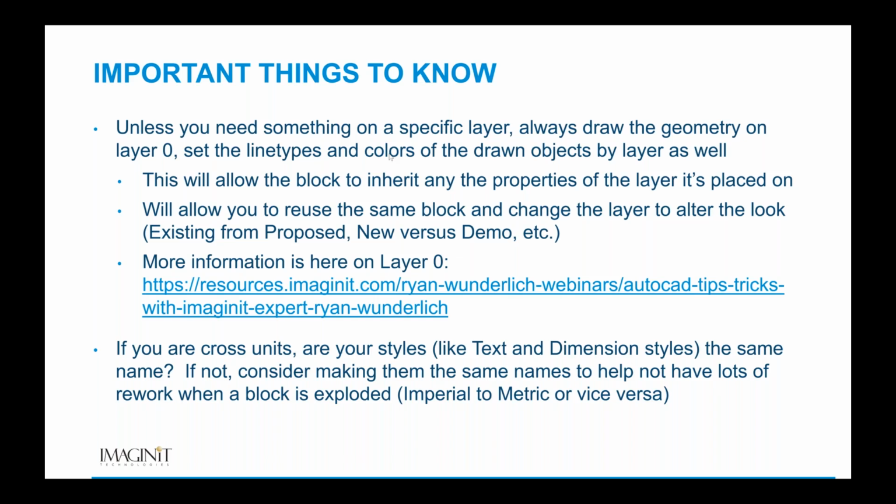Now, if you are cross units, i.e. if you work in both the imperial and the metric, are your styles, like text and dimension styles, the same name? If not, consider making them the same names to help not have lots of rework when the block is exploded. And I will give you a good example of that.